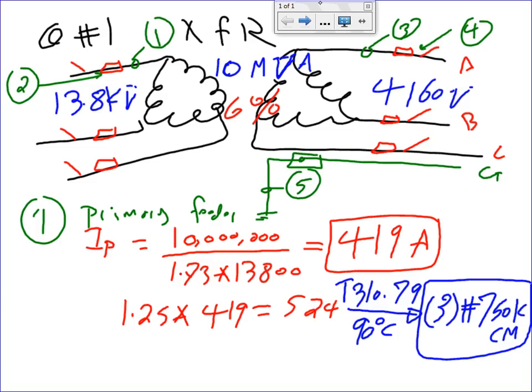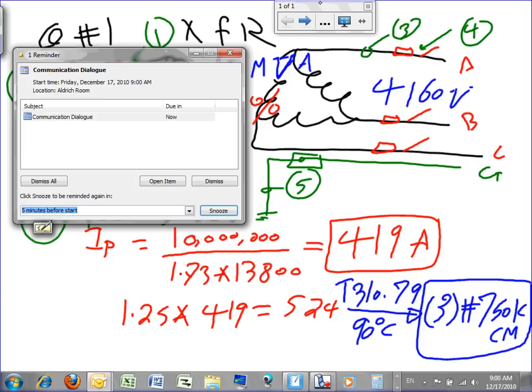And the only one that's single is 81, which gives you a single insulated copper conductor direct buried. If we want to put it in a duct, we have to go single insulated aluminum triplex. How about 3 single insulated copper conductors in underground ducts, 3 conductors per electrical duct here.